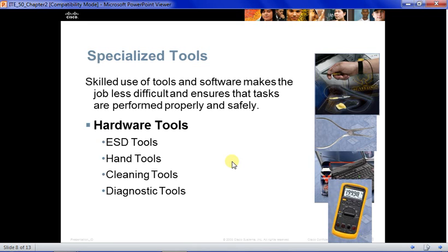And then the other end, with the little scissor-like connector, the pincher, you would connect to a non-painted metal surface of the computer. Your computer should sit on the anti-static mat. And again, there's a cable coming from that anti-static mat that you would attach to the non-painted surface of the computer.